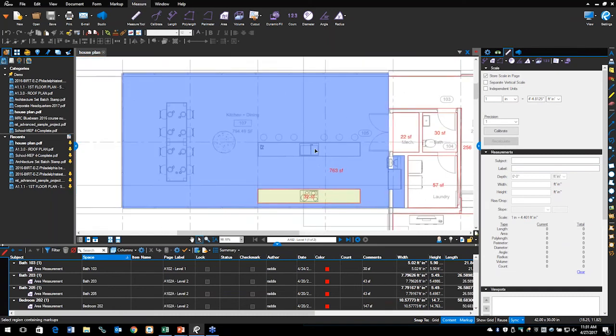Now, I'd had a room in here with the cutout for the column, and what I found was that Bluebeam doesn't handle a rectangular space with a circular cutout in the middle of it very well. It tries to attach things together, so what I did is I simply deleted that particular room when I outputted it and basically retraced this inside of Bluebeam.